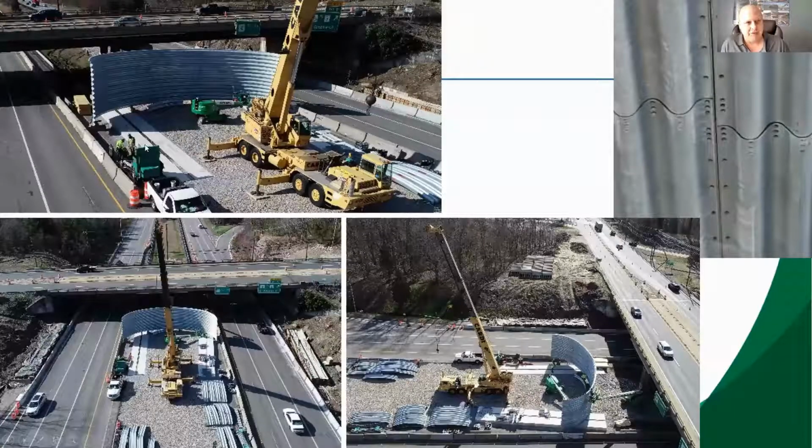And then I'll just wrap things up with snapshots from a transportation project in the eastern part of the country. Hopefully I'll get to do a case study on this one again soon, but this was twin 63-foot span arches for a temporary bridge to use as a bypass during replacement of the existing bridge in the background here. So the contractor built these in 17.5-foot long sections. And because of limited road closures, he would build this during the day, and then they would set the sections at night when they could close the road.